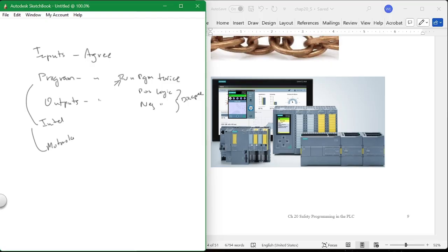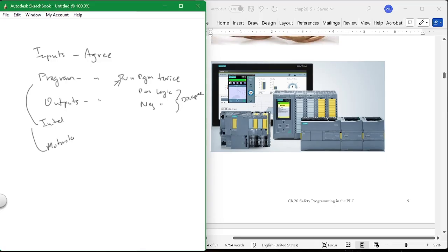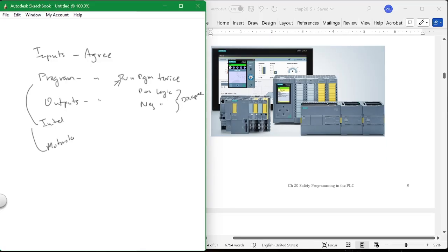I don't know. Now, if you look at a processor and you see these yellow designations, that means it's a Siemens safety processor, or it's a Siemens safety IO, whatever. So this would be the processor. It's got the yellow, and here are the safety IO cards. Now, you can have non-safety IO cards attached to a safety PLC. You can use the regular cards that are not safe as well. And there's no reason not to do that, because you can have non-safety stuff running in the same processor as safety stuff. All right?